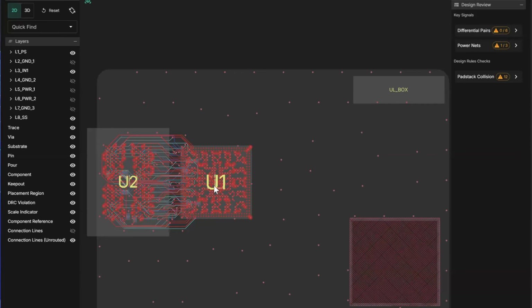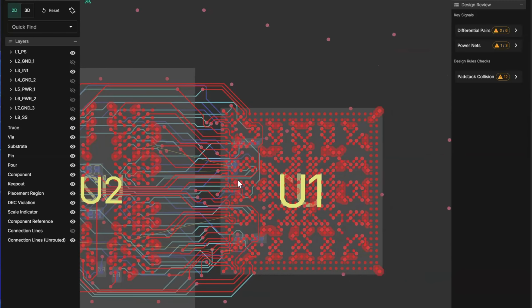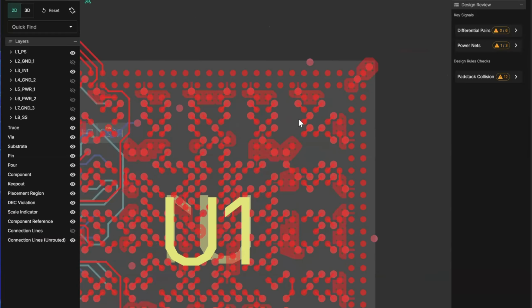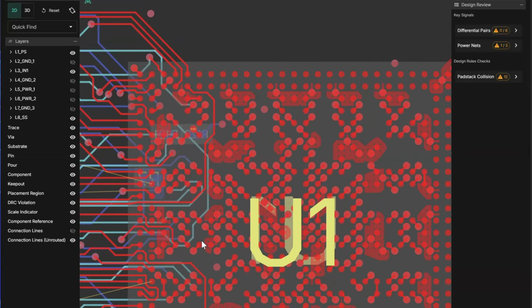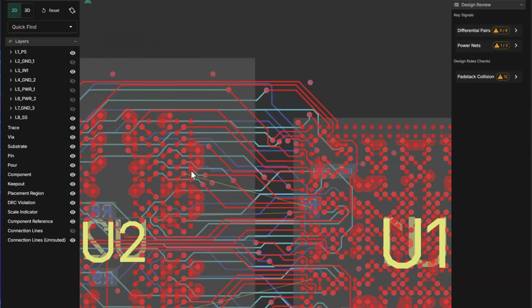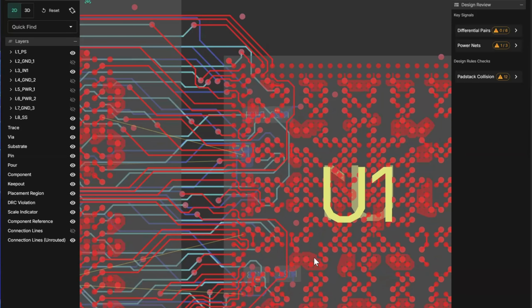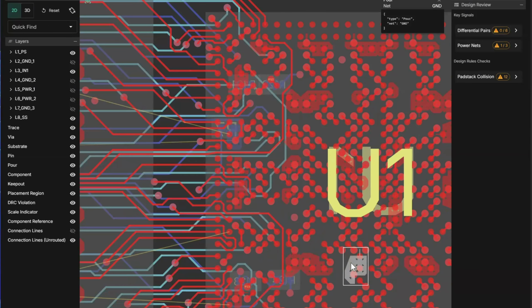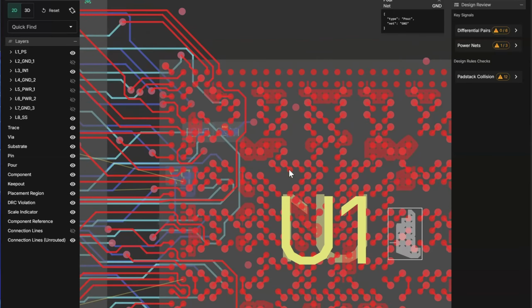Beautiful. Excellent. So this is an example of, I think, probably the same IMX8 and DDR4, but just on their own on this board. And what we're seeing here is a fan out for both sides. We're seeing a fan out for the CPU section, obviously with the unnecessary parts trimmed that we didn't need in the rest of this demo. Same thing for the memory section, and then the rest of Quilter dealing with how to hook up to that. And as a nice little bonus, you're seeing what we've been doing and talking about with some of the pours to get some of the better stitching here for the grounds and the power sections.